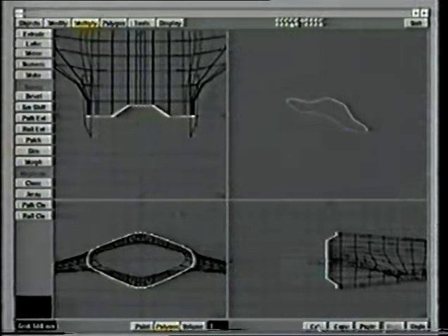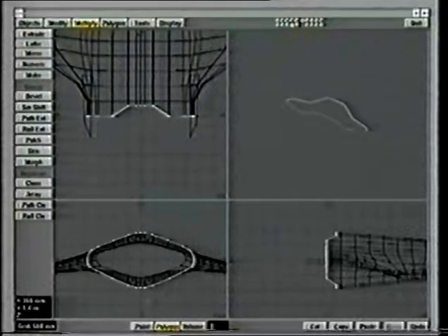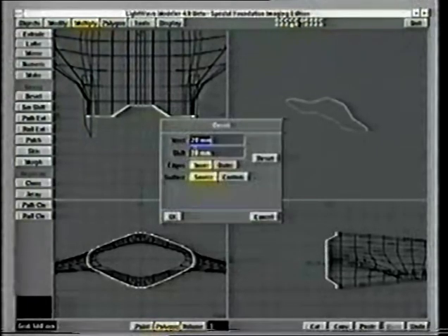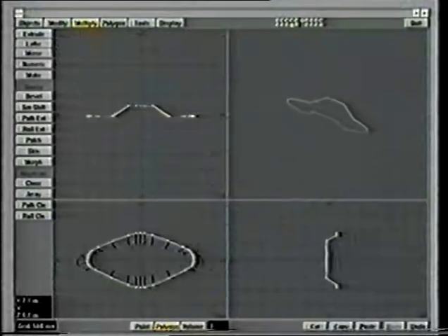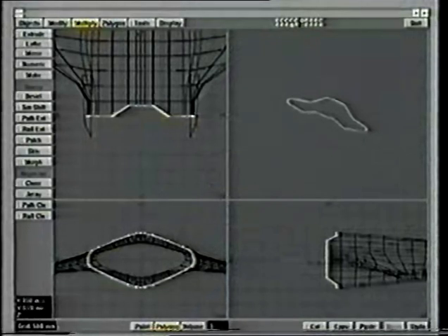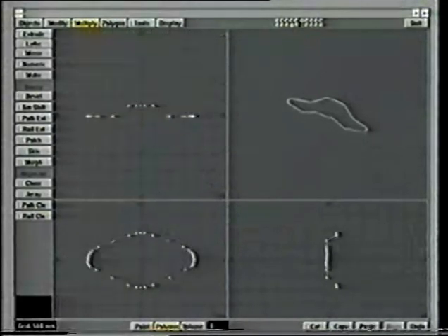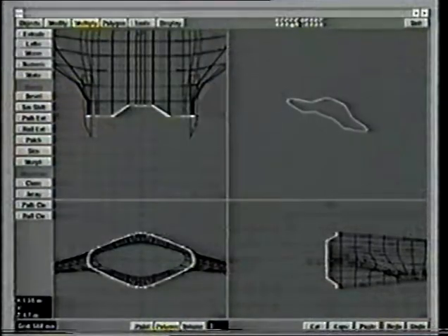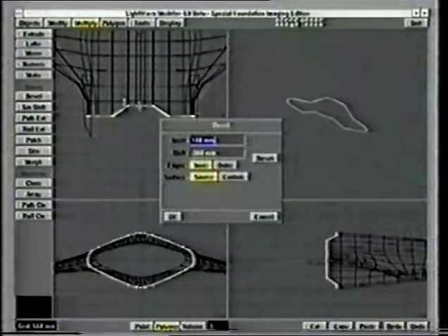And once again what we're going to do is cut it, paste it back in again, and then use the polygon select because it's the only polygon in there with more than 4 vertices. So I'll bevel it again, inset 20 millimeters, shift -20. Okay, and we'll cut it and paste it. Okay, so what I'm going to do now is use the W key to reselect that polygon and then bevel it once more to get the inner faces.